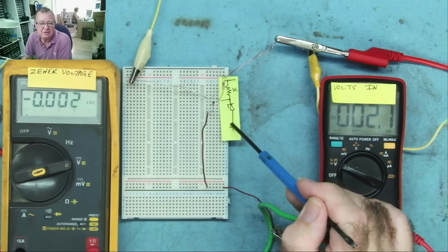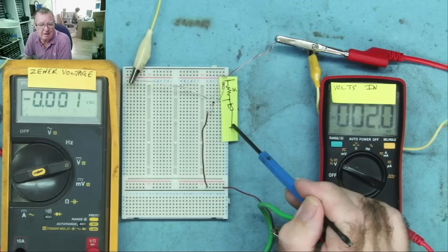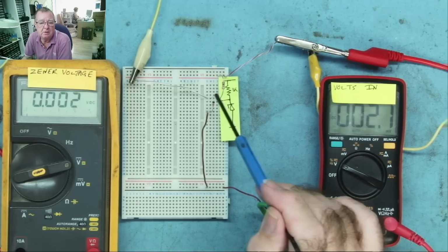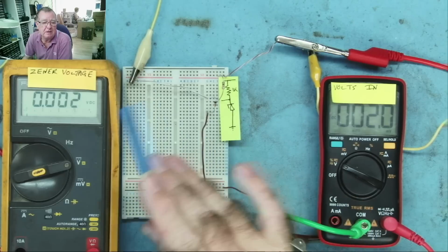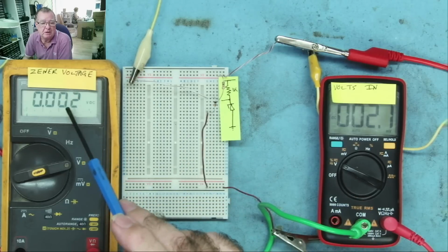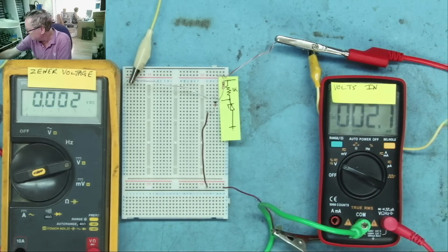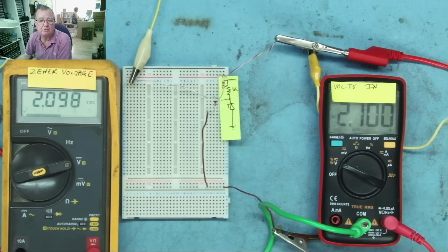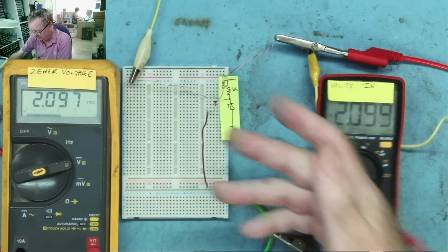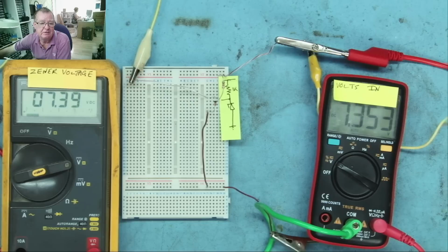So a Zener diode actually connects in the reverse direction to a normal diode. It's the reverse breakdown voltage that sets the Zener voltage. So from the junction of the resistor and the diode, I have a wire going here to this multimeter. So this multimeter is measuring the voltage across the Zener, and this is measuring the input voltage. Now let's see what happens. So I'll turn the supply voltage up, about 2 volts now, and you'll see that the voltage across the Zener and the voltage across the resistor are basically the same. And we can continue to increase the voltage. This is a 12 volt Zener.